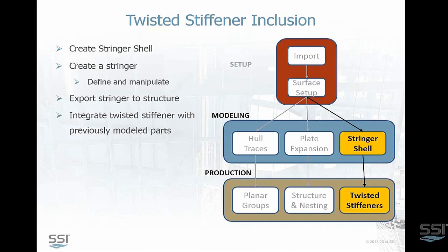It's recognized today that we don't always add the stringers right at the beginning of modeling, and so it might be that frames have been built up, there's plate parts pre-existing by the time that stringer is modeled, in which case it actually is intersecting previously created plate parts, and we want to demonstrate how quickly we can produce a cutout from that situation.